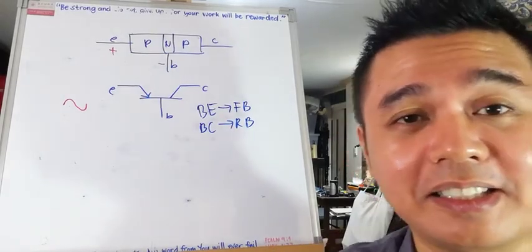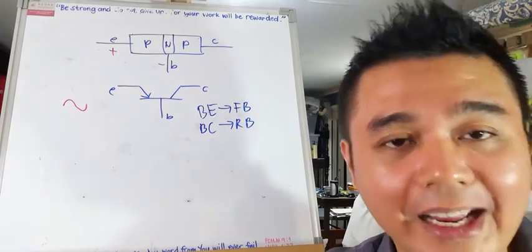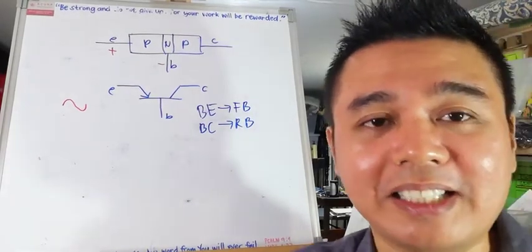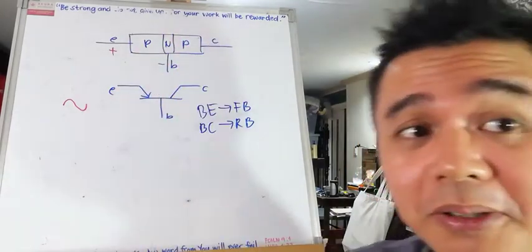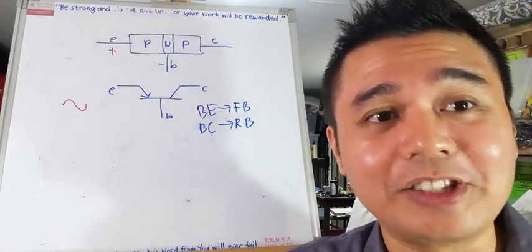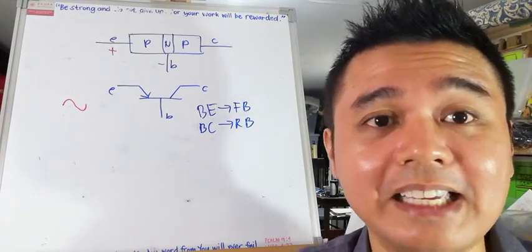Earlier, we got the AC resistance from Shockley's equation. So we have R AC equal to 26 millivolts divided by I sub D. But it is not a diode now. It's a transistor. So the name for our R AC is new.